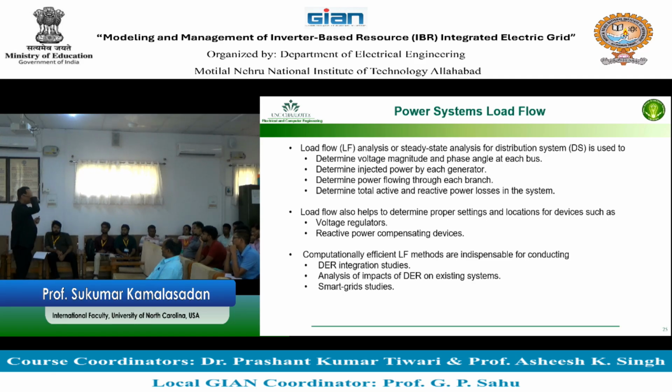You can put a device on a specific location where the voltages are low or high to balance that voltage. For doing that, you need to know some tool. You need to have some tool to run. The main purpose of the power flow is basically that. It's actually done during design, or for planning purposes.